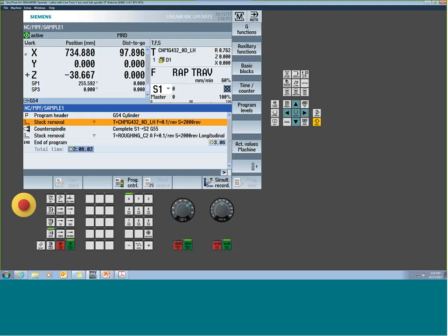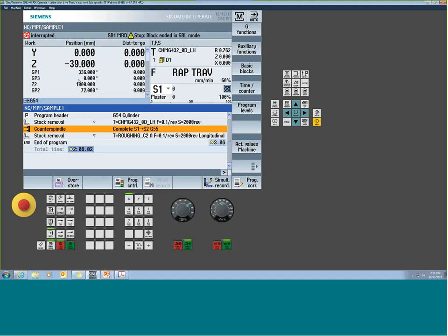Comes through, runs as normal, does its transfer. Now I'm back. So if I'm running, and we'll do a little single block. So I'm doing my cuts. Now I'm going to do the counter spindle transfer, right? So if I look at my axes, Z2 is still at 1,000 millimeters. The machine is going to auto-calculate where it had to go. It figured out that it had to move to 355 millimeters, but that's going to be based on the work offset that I wrote and the appropriate chuck dimensions that I have. That's why they're so critical.